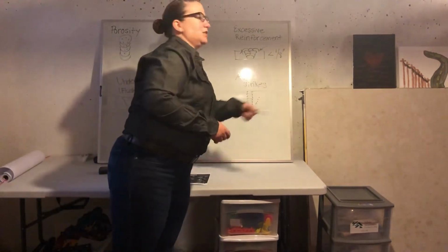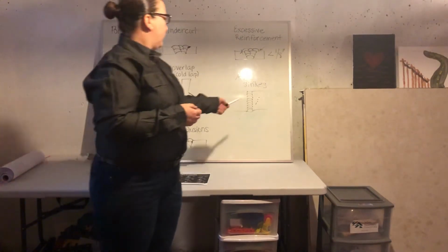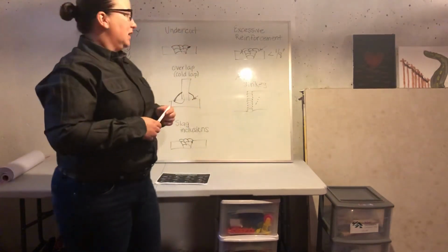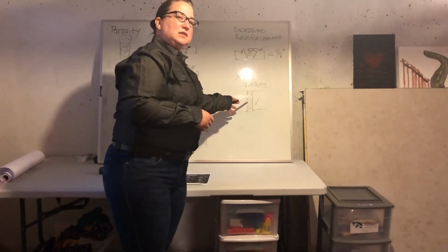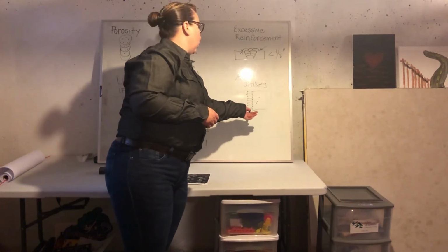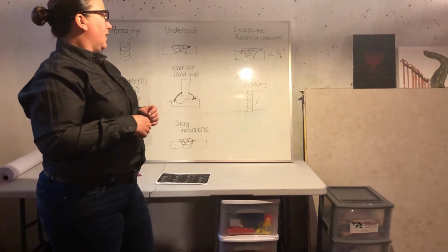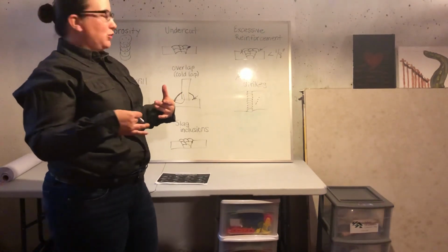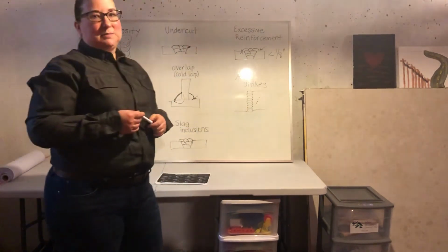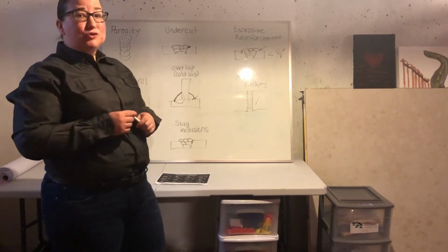Next, arc strikes. Arc strikes are completely undesirable in welding. They can actually affect your base metal and cause it to become weaker where you've struck the arc against it. An arc strike is defined as any sort of strike outside of our groove or our weld joint. So this is left over after we're done welding. We all aim for that nice pretty weld, and then nothing ruins it more than having that arc strike in the base metal right outside of there. So that's an automatic non-visual pass.